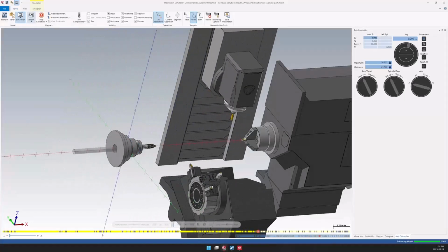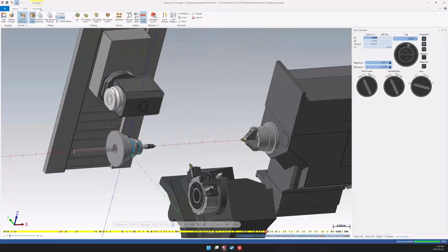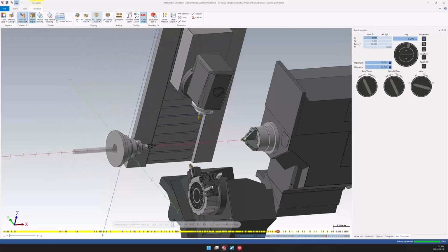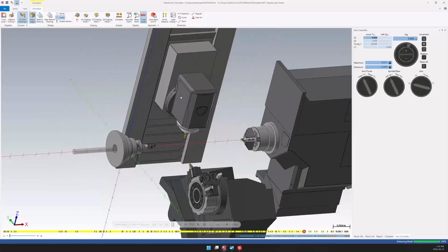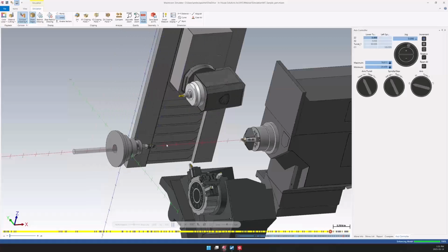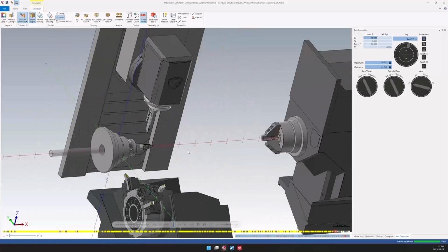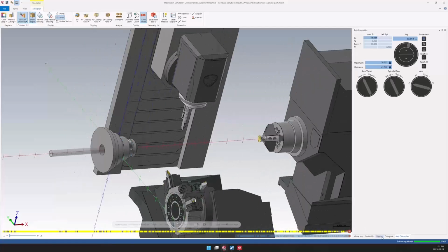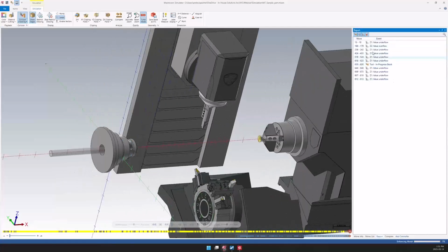You'll be able to use different view sheets, collision checking, clips or compare for all of what you need. You can get proximity alert, you can get collision as well. So you get this whole report here. You can get over travel values as well based on machine travel.